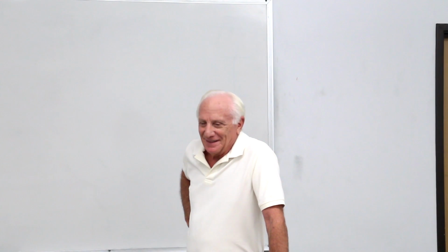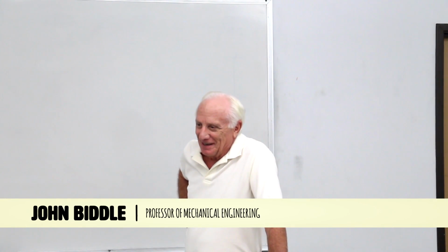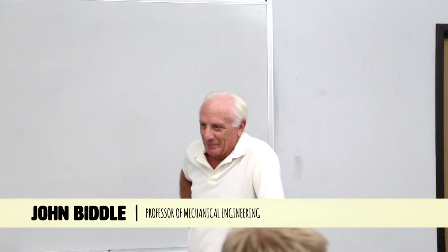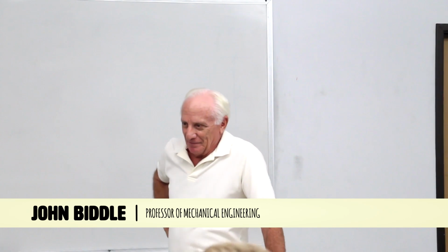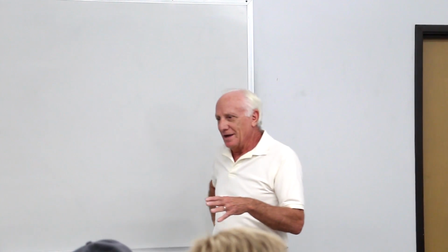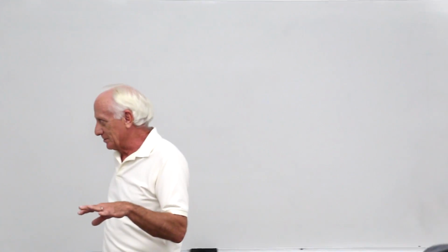One last time, chapter 5. Okay, we're covering 3 different basic laws of fluid mechanics in chapter 5. Using the Reynolds transport theorem, we take the basic laws written for systems and convert them into laws that we can use in engineering, based on the control volume, control surface approach.